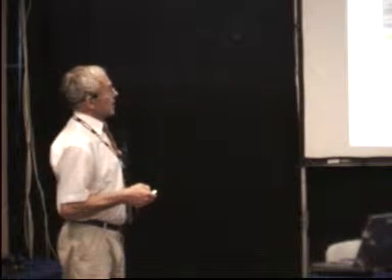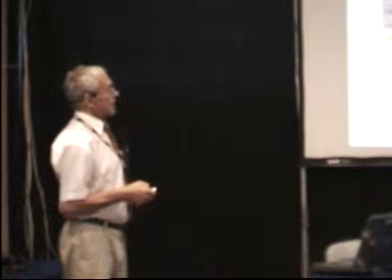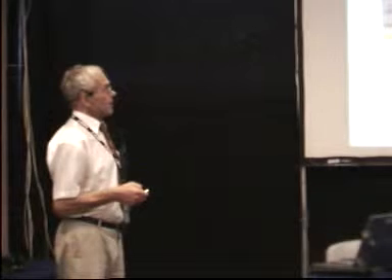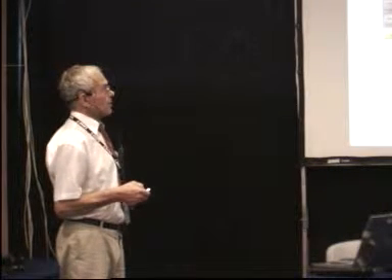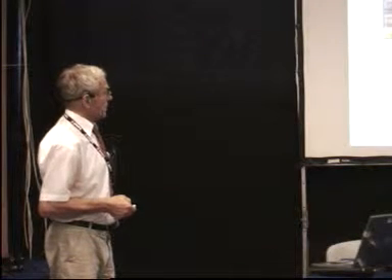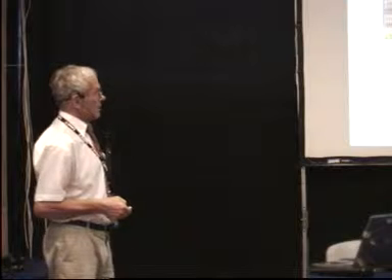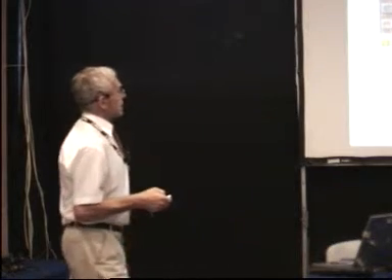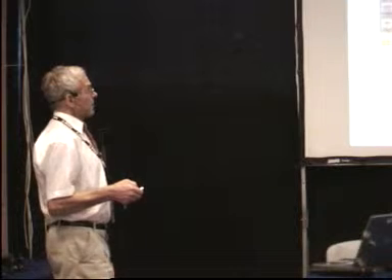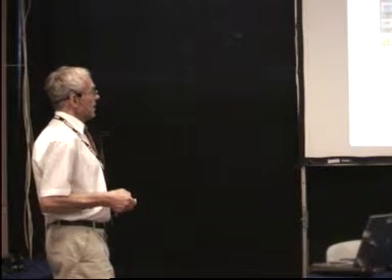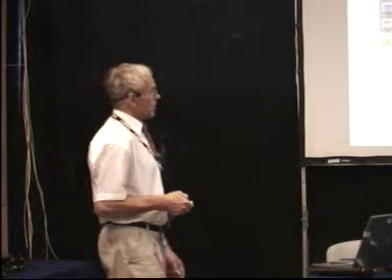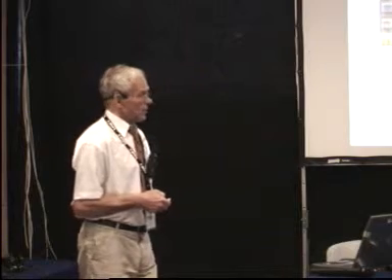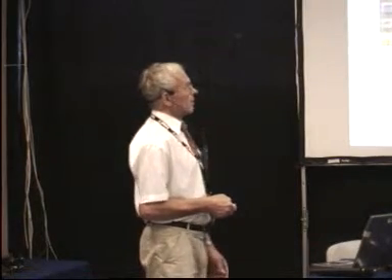This is the newly generated signal at the wavelength of 1549.32 nanometers, which corresponds to channel number 35 according to the ITU grid. This is the copy of the original signal, which was set at 1547.72. It was channel number 37. And here are another two eye diagrams. This is a newly generated signal at a wavelength of 1550.92, which is channel number 32, and here is a copy of 31. Unfortunately, we didn't have a demultiplexer which could demultiplex the idlers, because the idlers are above 1560 and we don't have a demultiplexer for this wavelength region.